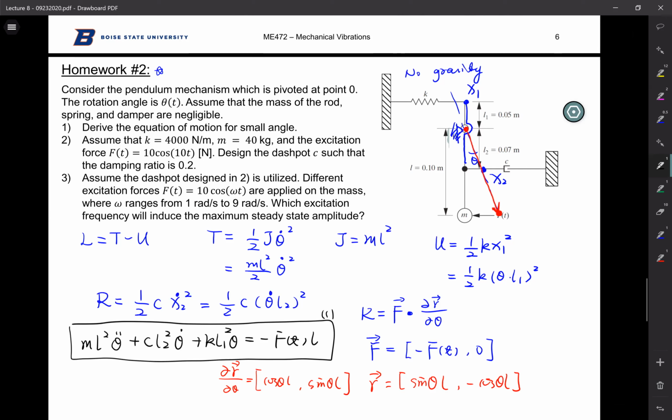So in your project, I figured out that perhaps you don't have to be that general. I already give you those MCK values. You already know if it's underdamped or overdamped or critically damped. You just pick that condition that matches the actual problem. You don't have to solve for all 3 conditions. Just pick the one that works for you. If you don't like symbols, you can also substitute numbers in and then eventually your analytical expression will be in terms of numbers, not in terms of symbols. That's also okay. Okay, cool. Thank you.